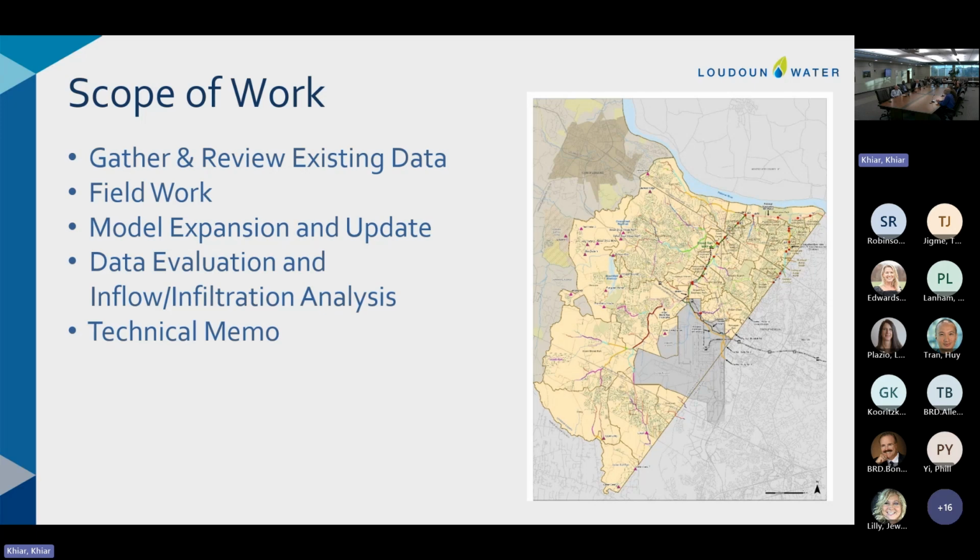The bulk of the work is really in the model expansion and then the data evaluation and the inflow and infiltration analysis. The model expansion I'll touch on a little bit more on the next slide, but it's primarily to get all of our pipes and all of our manholes, all of our pump stations, all of that built and included into our hydraulic model.